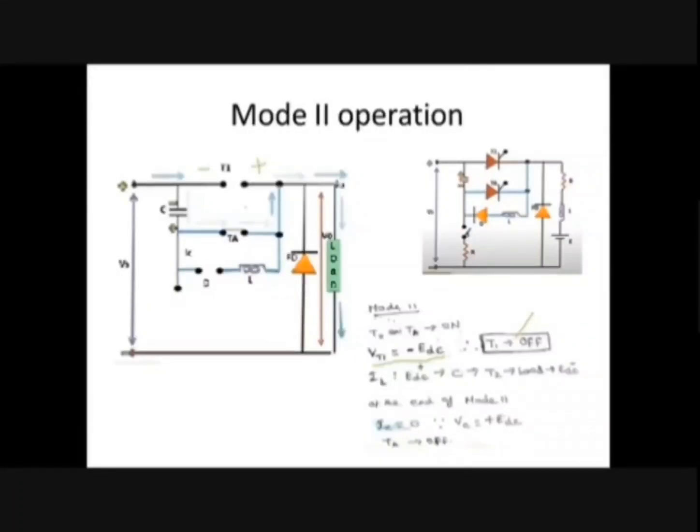This combination is otherwise called voltage commutation, and we have an auxiliary SCR, so it is called auxiliary commutation. That's why this chopper is called a voltage commutated chopper. Okay, now you understood how SCR T1 is getting turned off.